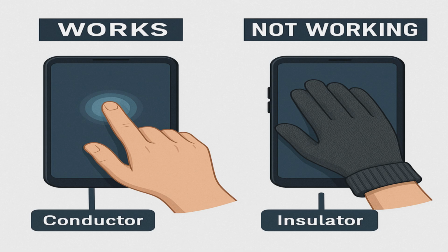4. Surface acoustic wave touchscreens. These use ultrasonic waves across the screen surface. When touched, the waves are absorbed at that point. The system measures the interruption to determine the touch location. Pros: excellent clarity, works with fingers, gloves, or soft styluses, long-lasting. Cons: sensitive to dirt or moisture, not ideal for outdoor use, more expensive than other types.